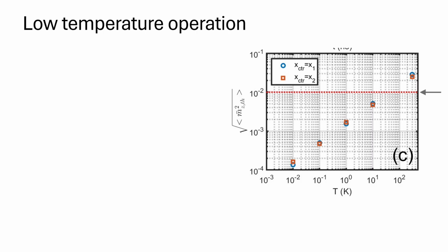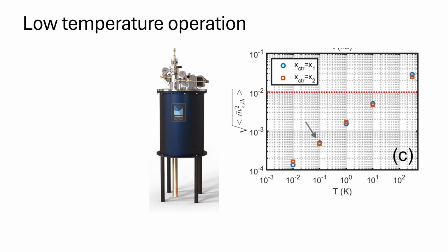In order to bring the thermal noise amplitude down to, let's say, 10 times below the operation amplitude, one would have to lower the temperature to 0.1 Kelvin. To bring the temperature to such a low value, one would have to place the magnonic chip inside a cryostat. Such act is totally against the principle of energy economy and spatial miniaturization of modern computing.